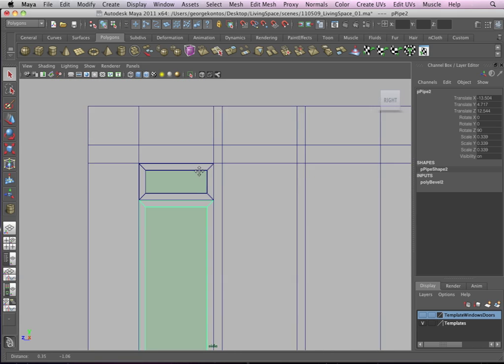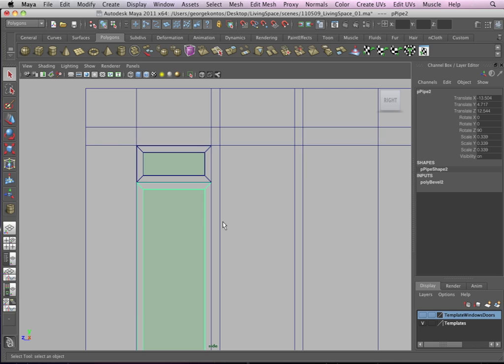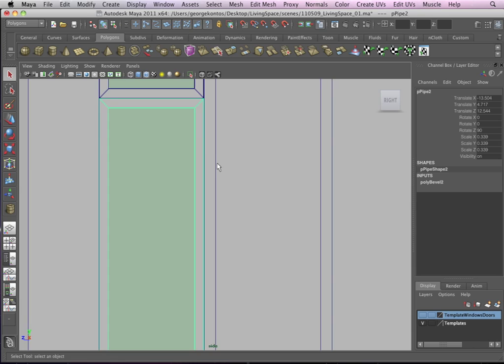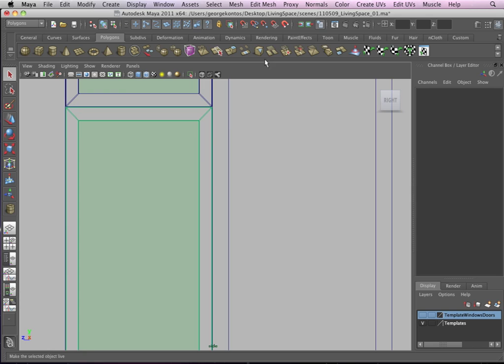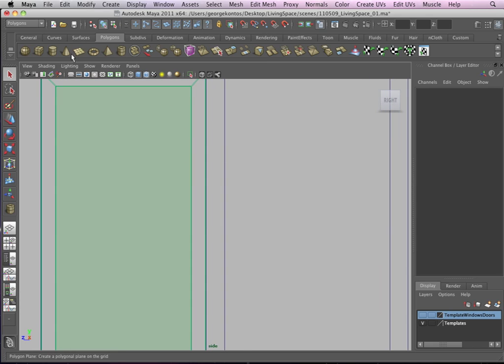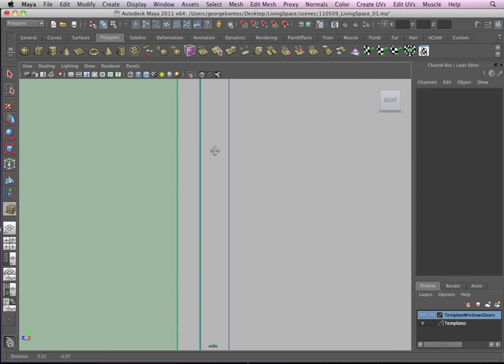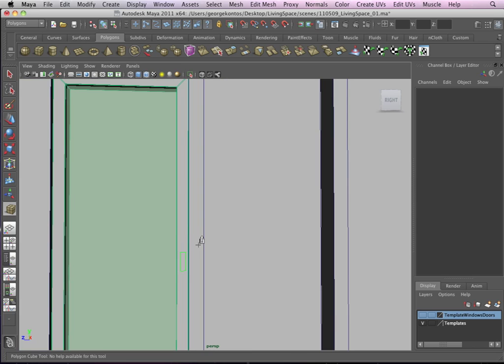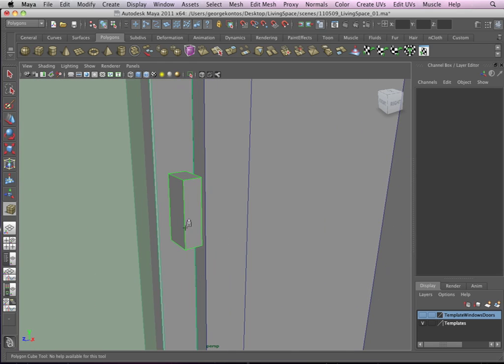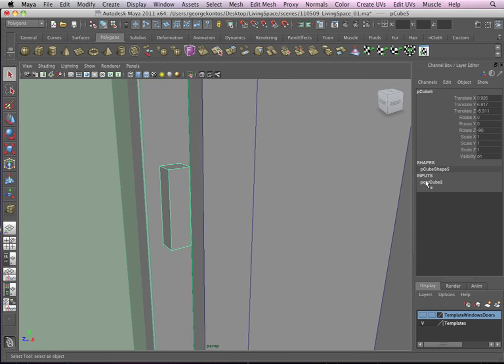Go to the side view, and remember on the city model that we used to make objects live with a magnet tool. We can work on making other objects on their surface. So that would be a very convenient thing to do here. So I'm going to select this object and make it live. If you click on that magnet, it becomes live. So I'm going to select a cube, go closer and draw it over here. Go to my perspective and continue drawing that cube. So pull the height out. And let's make more subdivisions along the width.